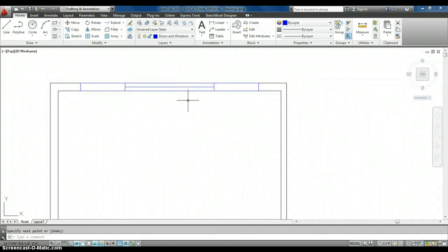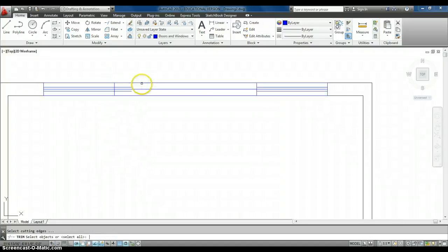And then how we draw a double hung window is we like to show 2 rectangles inside of the overall rectangle. That's kind of looking down at the double hung, and each one swings back and forth. So once again, I am going to draw from center to center, or midpoint to midpoint. And then I'm going to offset about 1 inch to each side, and that's going to give us those 2 rectangles that we see there. It looks like these lines went a little bit farther than they needed to, so I'm just going to go ahead and trim those up.